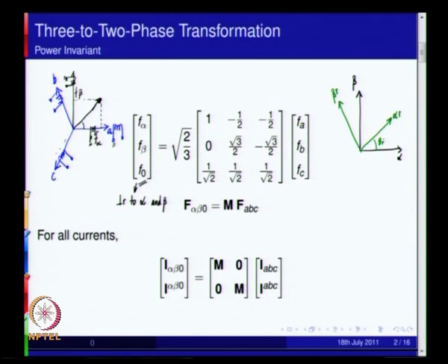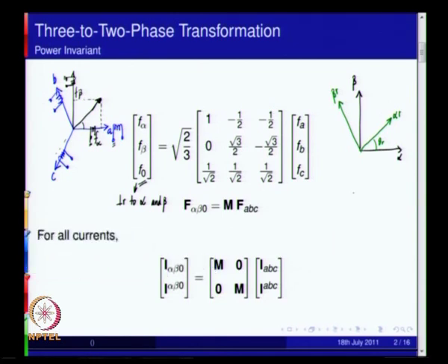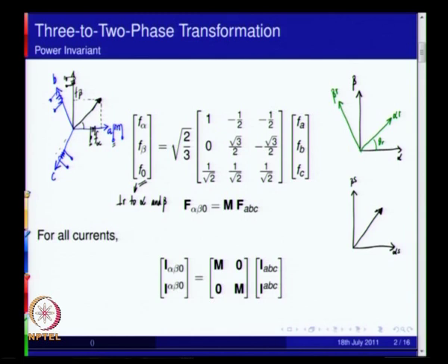One thing we must understand very well at this stage, that let us say you are looking at the stator alpha and beta axis. So you have the stator alpha, let us call it alpha s then, and beta s for the stator. We had looked at the net MMF generated by the three phases of the stator winding, and whether you consider the MMF source now to be along the alpha and beta axis or A, B and C axis, the net MMF is always the same.